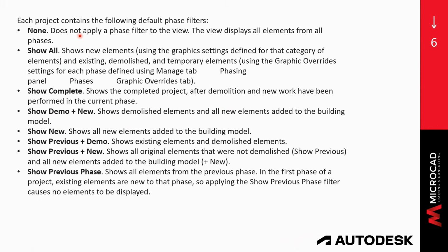When you choose the show all filter, it's going to show all the new elements using the graphic settings defined for that category of element. It's going to show the existing, the demolished, and the temporary elements.